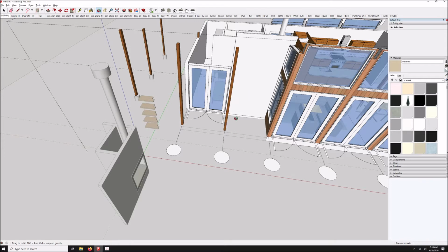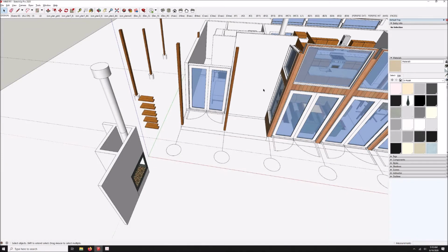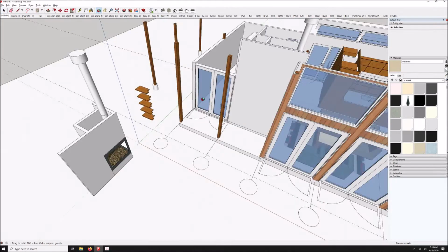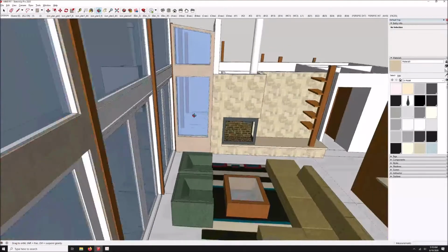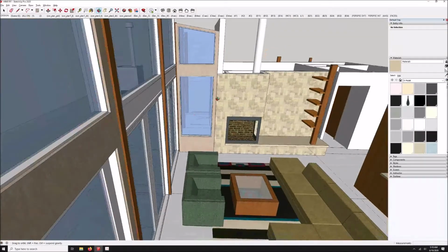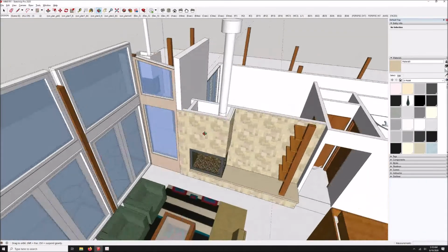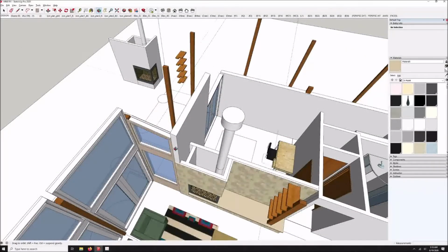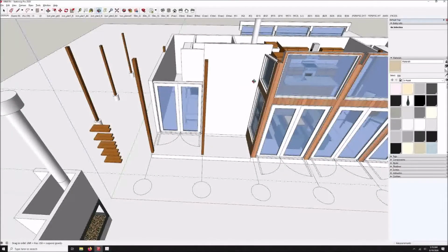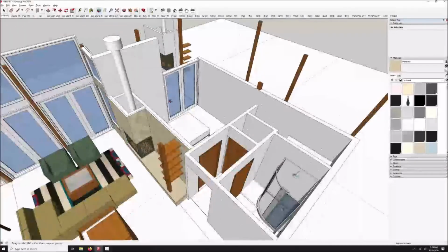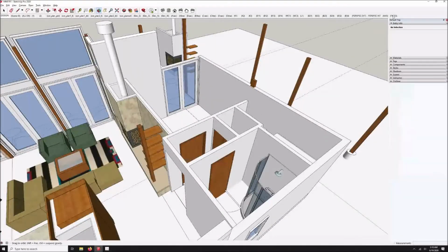This being a patio for this bedroom, I felt that it was not appropriate to have the vent coming out of the wall right here. I was also concerned about seeing the vent through this window. It's a big metal box, and it might not be nice to see it looking out this window. So another option is to come up a little higher and go out above head level, come out about here. And that's an option I'm going to look into further. The final choice is to go straight up, and that has the advantage of, let me turn the roof on.